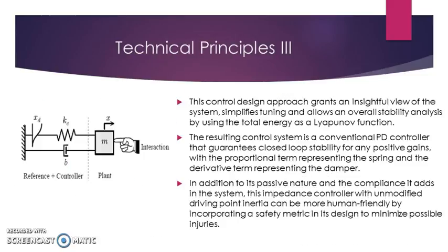For technical principles, slide 3. This control design approach grants an insightful view of the system, simplifies tuning, and allows an overall stability analysis by using the total energy as a Lyapunov function. The resulting control system is a conventional PD controller that guarantees closed-loop stability for any positive gains, with the proportional term representing the spring and the derivative term representing the damper.